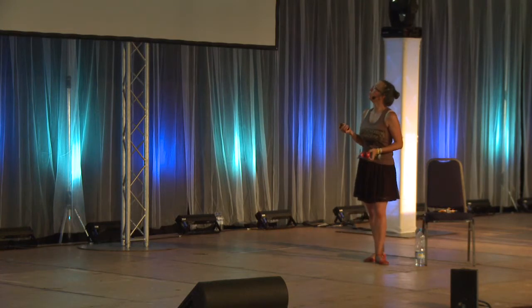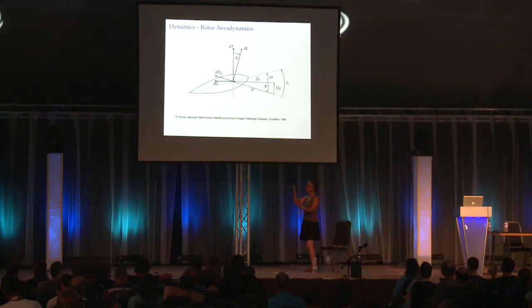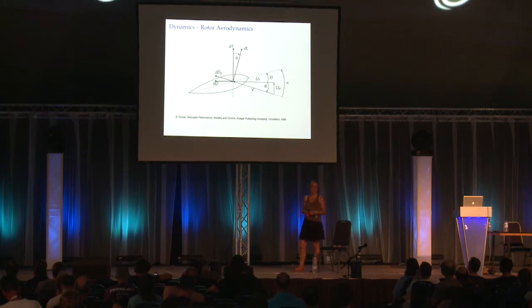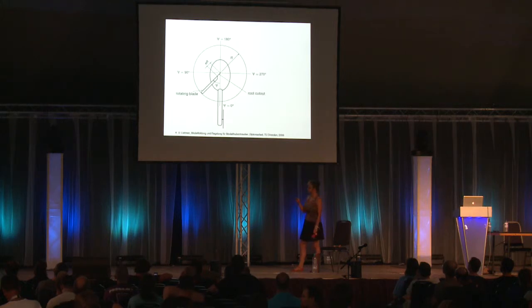So another theory would be blade element theory. We cut the blade at any length, so just a cut through the blade. And basically like finite element theory, you integrate over the length of the blade. So here's the first difference between helicopters like this one and the nice tricopters and quadrocopters out there.